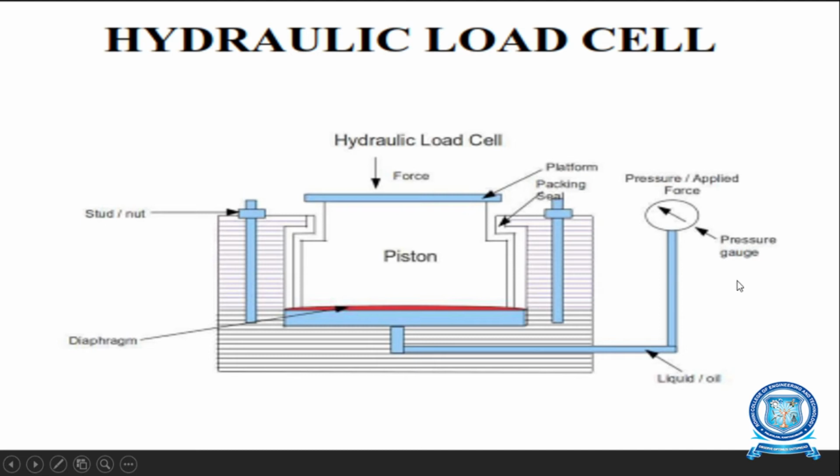The major limitation of this type of load cell is the need for minimization of friction between the conventional piston and cylinder arrangement, and also the requirement of packing and seal to avoid leakage of the oil. So these parameters are unpredictable, so it is very difficult to obtain.